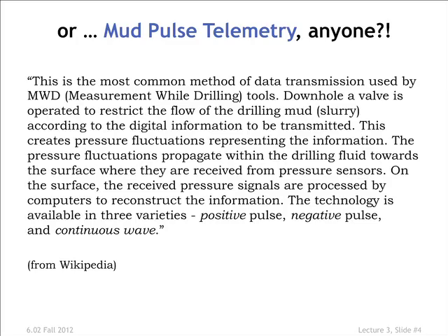Here's one you may not have thought about, mud pulse telemetry. So when you're drilling for oil, you'd like to get information from the drill bit at the bottom. And normal electronics doesn't work too well because the temperatures are fiercely hot down there. You need that information to help you steer the drill bit, to get information about what sort of rock you're going through and all of that. So they actually seriously do use pressure pulses in the slurry that's cooling the drill bit to try and convey information back to the top. They'll modulate the pressure down at the end of the drill bit and hope that you can detect it at the top.